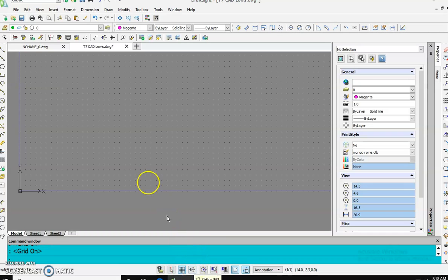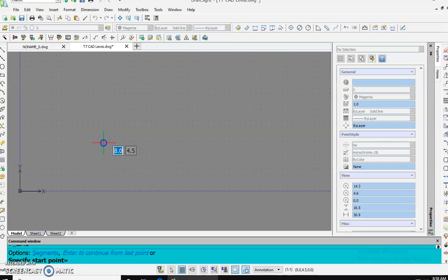And then there's this one right here. This is called Ortho. Now, Ortho is a very specific type of drawing. So if I actually click on the line icon and I want to go to draw, you can see you have a lot of freedom and a lot of angles you can go. Now, if you want to draw a perfectly straight line, you sort of have to zoom in and really dial in your eyesight to see, is that straight? By turning on Ortho, it only allows you to draw straight, horizontally, or vertically. No matter where the cursor is. You can see my cursor is way up here, but the line is straight no matter what. So this is a nice feature.